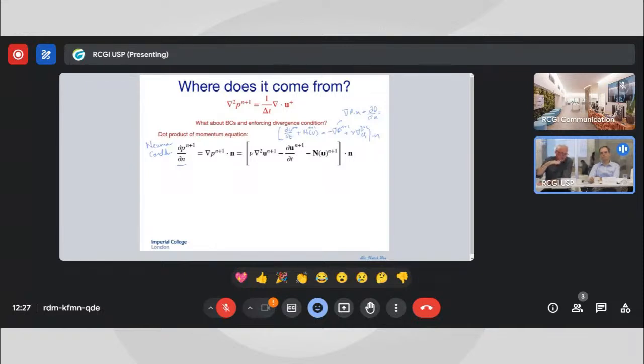Let's take the values n and n minus 1 and push it forward in time. So that's my first step here, to replace n plus 1 with n. But the other challenge of this scheme is, I've already admitted that when we set the pressure Poisson equation, we didn't set the real velocity at n plus 1 to 0. We set this u hat, a u star quantity, to be equal to 0.